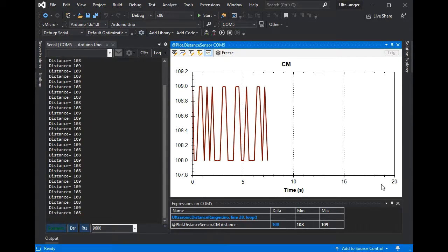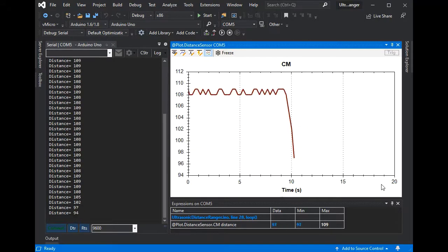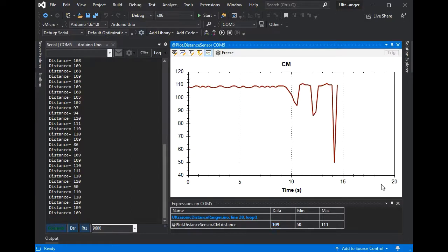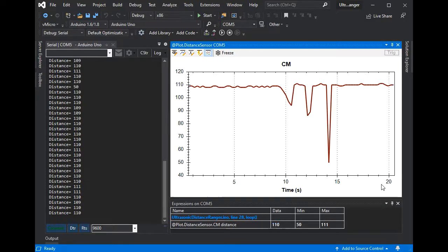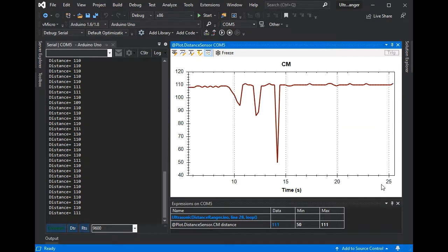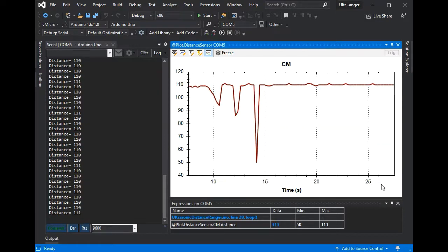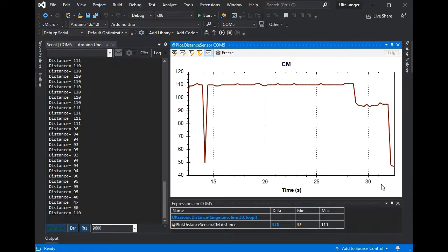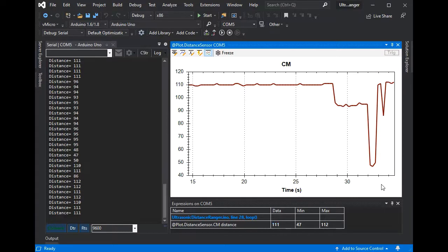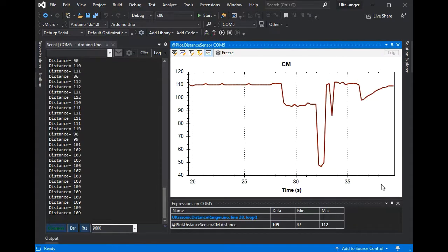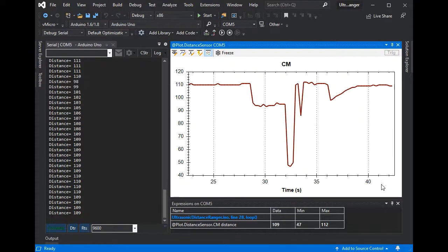going on. So here we can see nothing's moved. Oh, there we go. So we've opened the door, closed it, but these are very short dips, so we're going to try and reposition it so that we get a longer dip, something we can be more sure of in our code. So I'm just going to physically move the project to be in a better position by the door and try it again. And as you can see, we've got a much bigger dip and a much longer dip, so we're more likely to have a positive detection using our project.